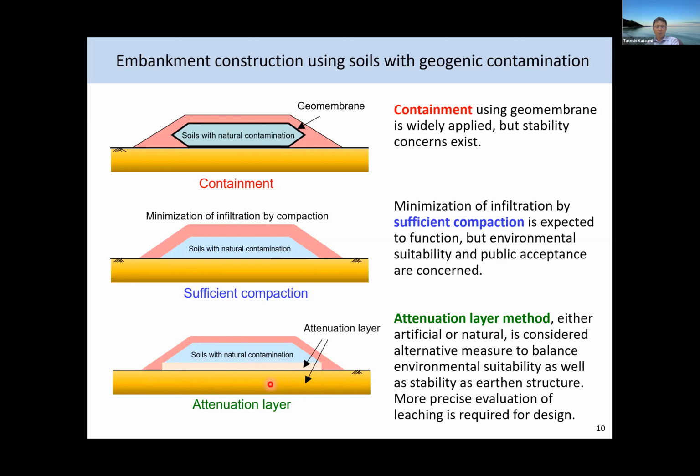But for this attenuation layer method, we need a more precise evaluation of design compared to a geomembrane method. For example, the leaching behavior should be carefully studied to decide the material and the thickness of the attenuation layer.